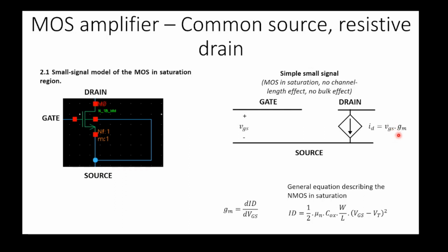Okay, next we talk about the parameter in this formula, gm. gm is called the transconductance, and for the definition of gm, please refer to my references. Here I just extract the information. The transconductance is equal to the derivative of the drain current with respect to the gate source voltage. How can we do that differentiation? Of course, in video one we also introduced the square law model, or the equation of the MOS when the MOS is in saturation.